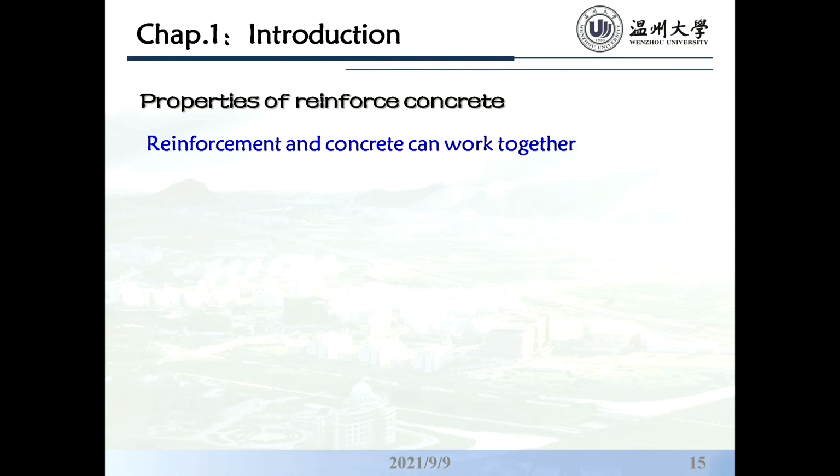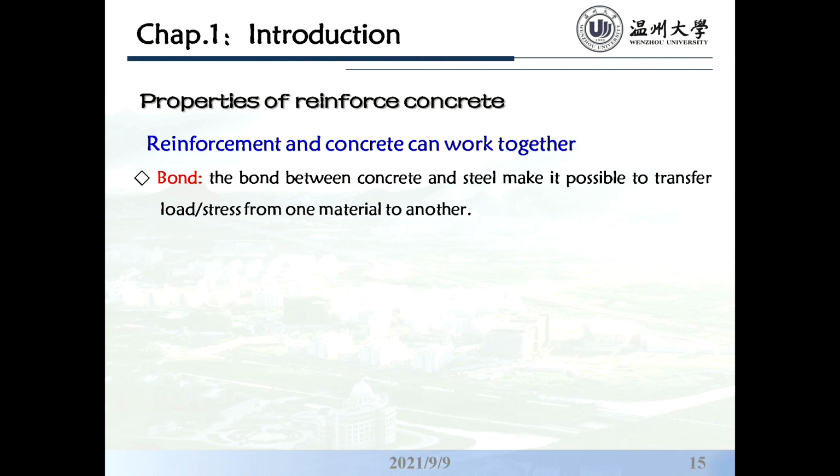And come back. Let's talk about the reinforced concrete. Right? Reinforced concrete. Someone will ask why here we use steel bars in the reinforced concrete. There are three reasons. One is the bond. Bond means that the load applied on the concrete, the concrete can transfer the load to the steel bar. Then that means the steel bar and the concrete can work together.